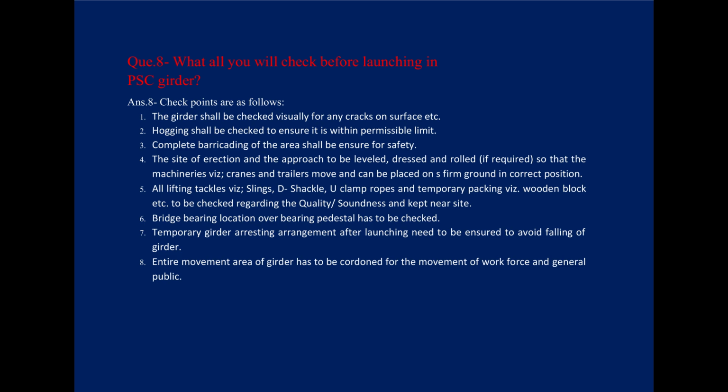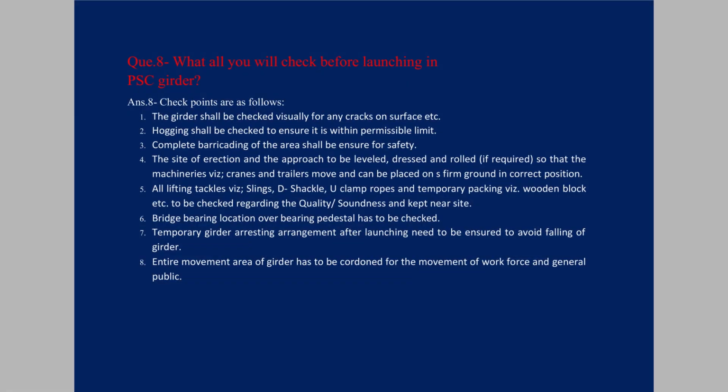6. Bridge bearing location over bearing pedestal has to be checked. 7. Temporary girder arresting arrangement after launching needs to be ensured to avoid falling of girder. 8. Entire movement area of girder has to be cordoned off for the movement of workforce and general public.